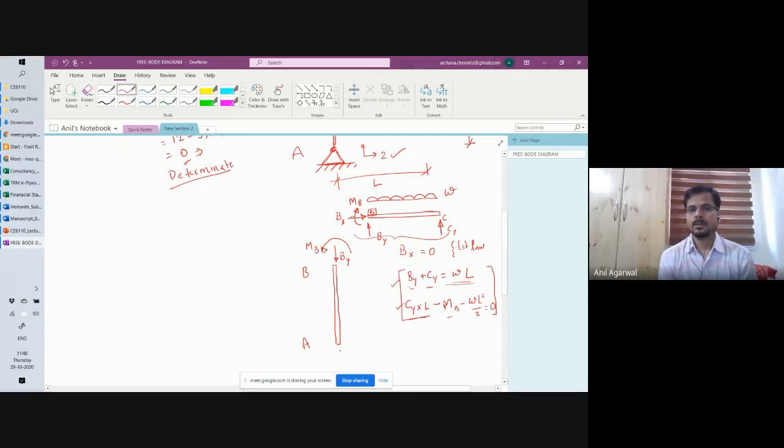Fine. And what kind of forces are available at A? I can have a horizontal force. I'll call it Ax. But I can have a vertical force. I'll call it Ay. Can I have any other forces acting on this member in any way possible?